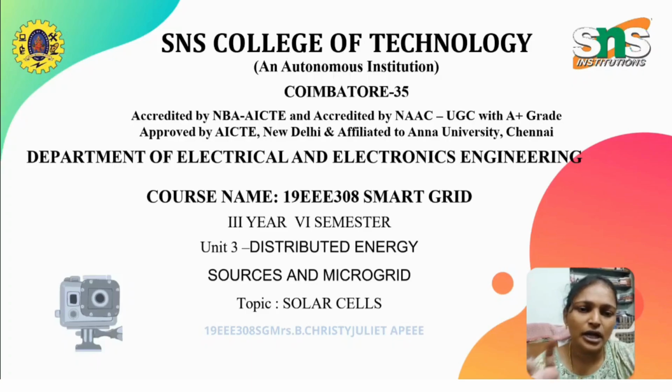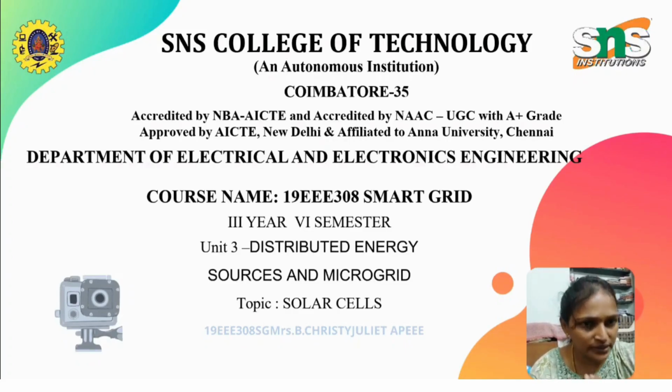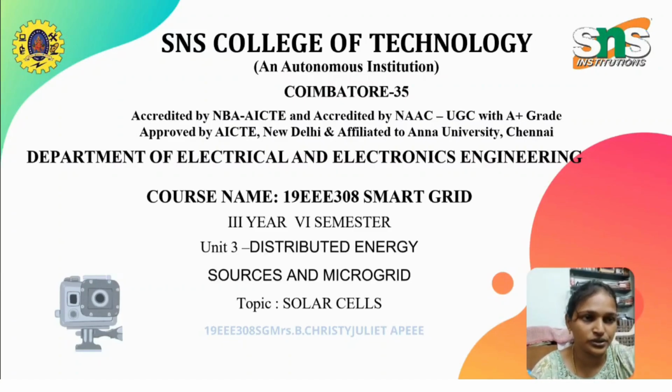So microgrids are a localized grid which has all the features of a smart grid, specifically meant for power transfer from renewable energy sources to a localized group of customers. And also, whenever needed, the surplus power in a microgrid can be transferred to the main grid through interconnections. And when a fault occurs, or whenever it is not required, it can operate in an islanding mode. That is the main feature of a microgrid. So microgrids are specifically meant for renewable energy sources.